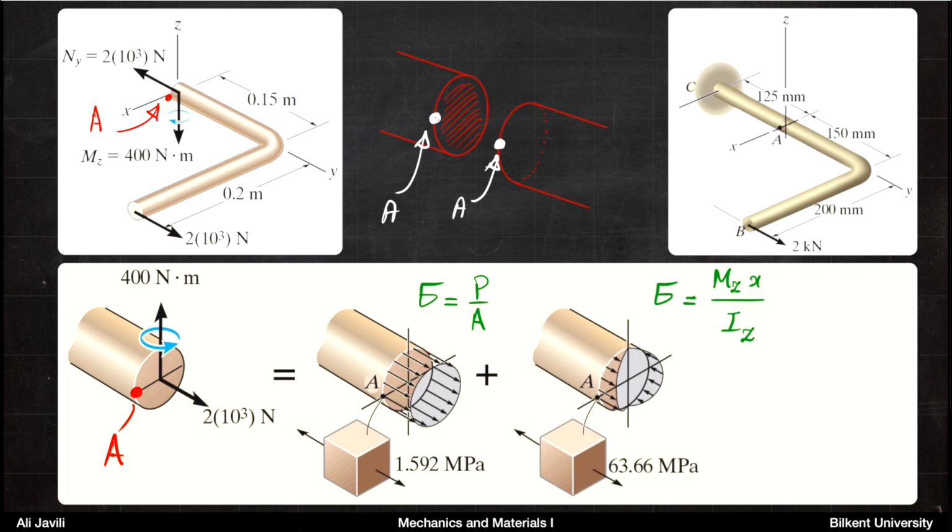Now on top of that, you would have the bending moment, and you can imagine that the bending moment you have here is with respect to the z-axis. So this is the z-axis. So your flexure formula would be sigma equals M with respect to z-axis divided by the moment of inertia with respect to z-axis, and then the distance from the z-axis.